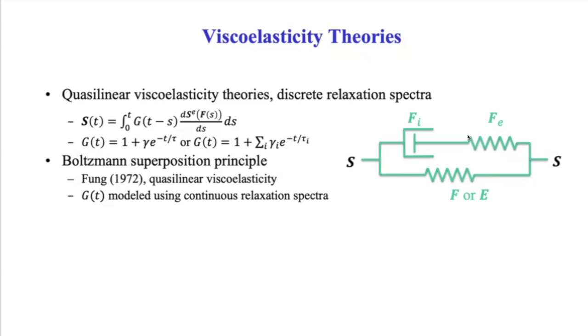So it's kind of important to understand that quasi-linear viscoelasticity is already breaking the assumptions inherent in this spring and dashpot model, because the differential equation that led to this integral equation was based on the assumption of linearity. But everyone in viscoelasticity theory is very comfortable saying, it's fine, we're going to make the spring nonlinear.